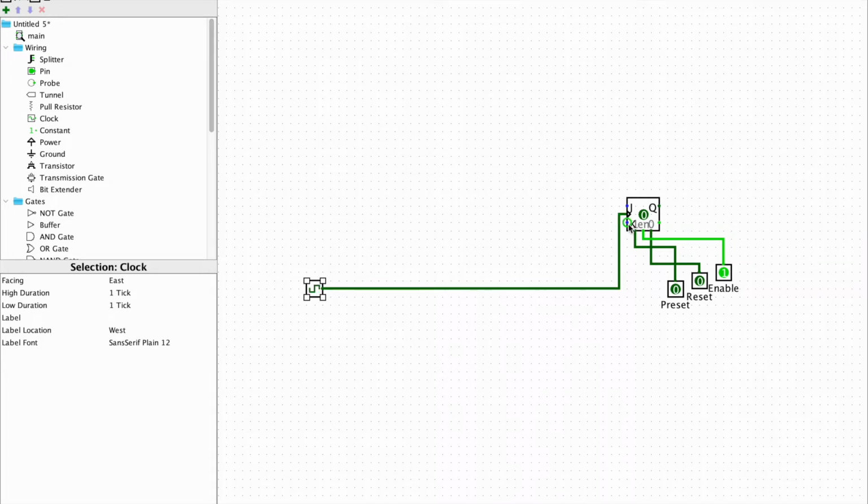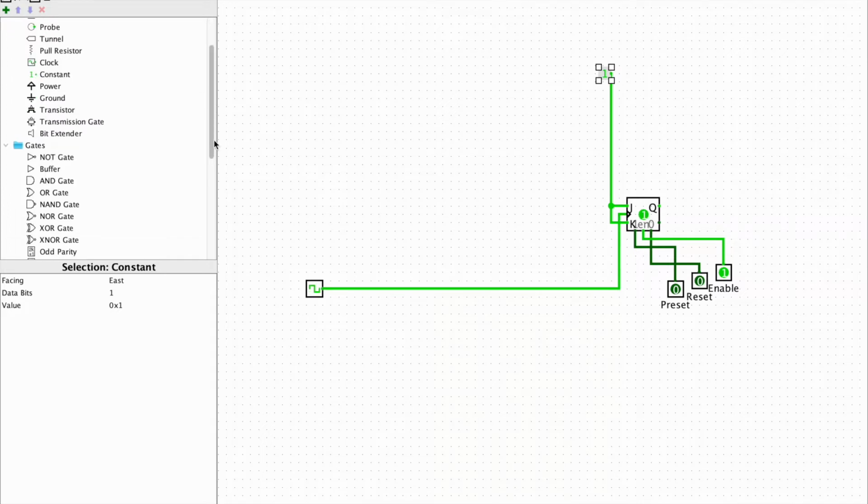Okay, perfect. Now we also know that the flip-flop toggles between states when the value of JK is equal to 1. So we set both the value of J and K equal to 1, and this will be our least significant bit.